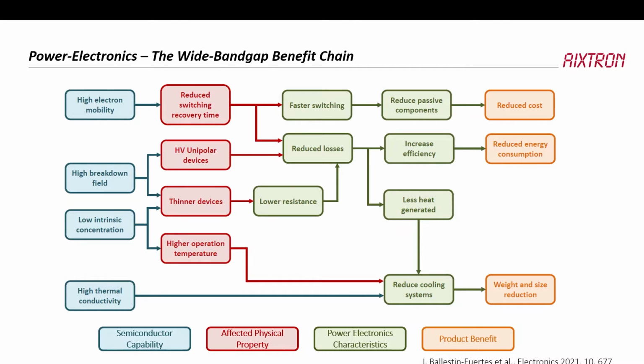It's not just important that the transistor becomes less expensive. You can alleviate some of the higher cost by reducing the parasitic, or let's say, peripheral components such as inductances and capacitances in the circuit. Because usually the higher the switching frequency, the smaller those become.